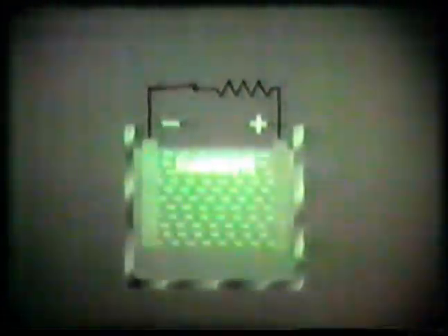In an aircraft battery, the electrolyte is a chemical solution. The chemicals used in lead acid and nickel cadmium are not the same, but in both types, the electrolyte provides an electrical path between the positive and negative plates. Thus, when a load is connected to the battery terminals, a complete circuit exists in the battery via the electrolyte. This makes a continual flow of current possible and greatly increases the electron pressure from the negative terminal toward the positive terminal.